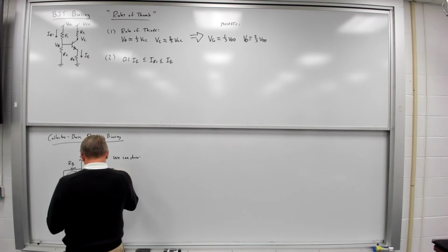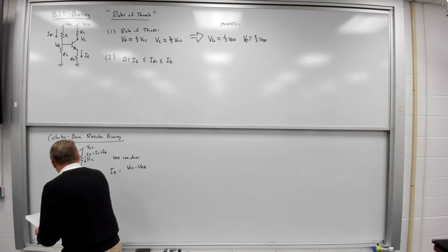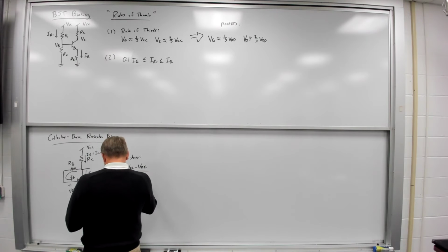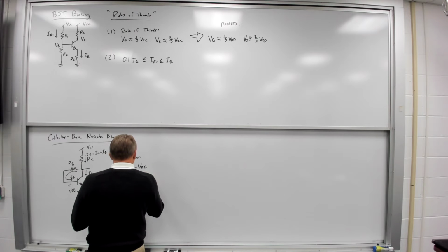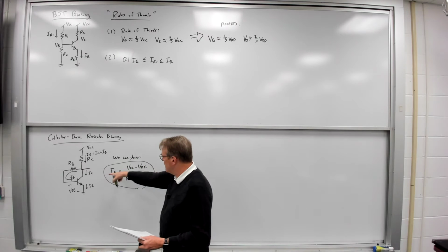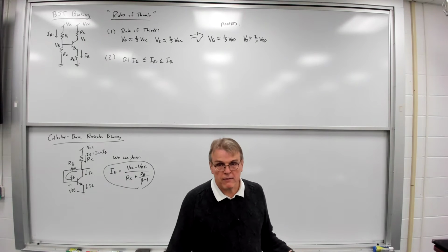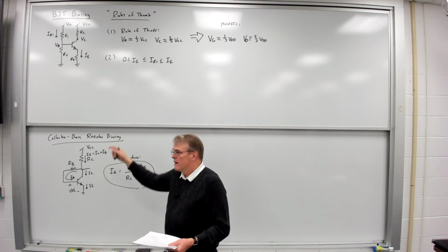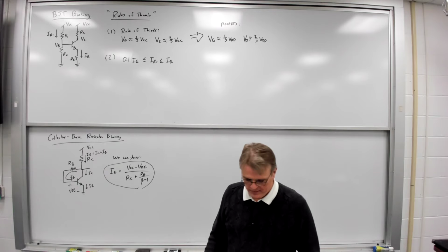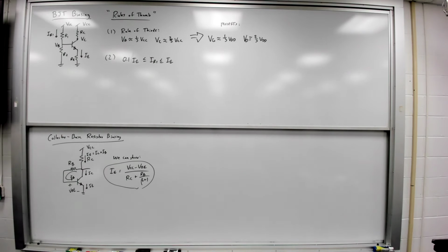And you can prove in this case that IE will be equal to VCC minus VBE. Of course, VBE is this voltage here in the circuit, the base emitter voltage, divided by RC plus RB divided by beta plus 1. So you can actually go through and prove that this is the correct equation to calculate that current. And you can also prove, although I'm not going to do it, that this circuit, just as with the collector gate bias circuit, tends to be more resistant to biasing variations due to component parameters. All right? So you can use this.